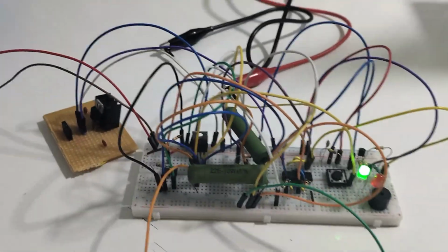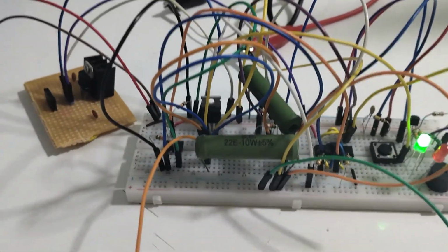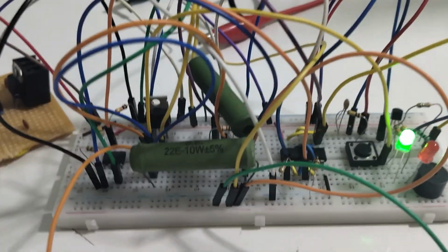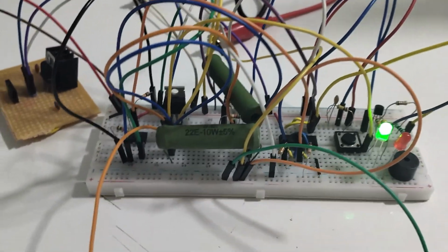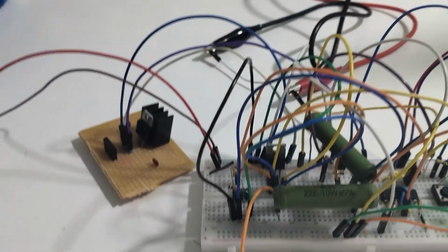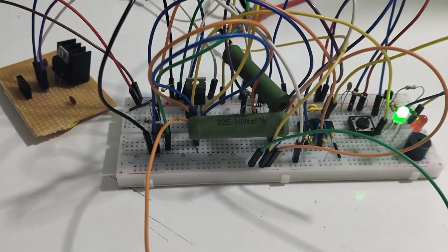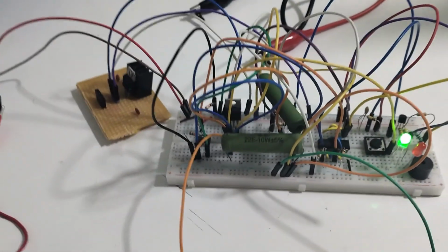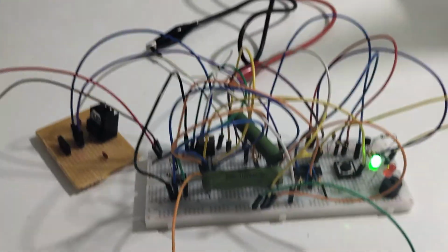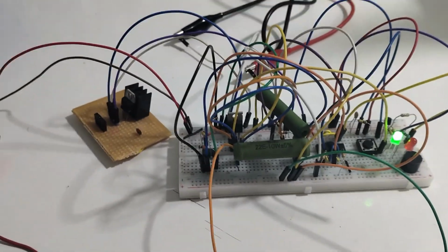So it's a very versatile circuit and fully discrete. There are no digital components involved here, so the BOM cost is going to be much lesser than, you know, implementing maybe a Hall effect sensor or something of those sorts. And if it's just a simple power supply or something like that, this circuit would work perfectly.